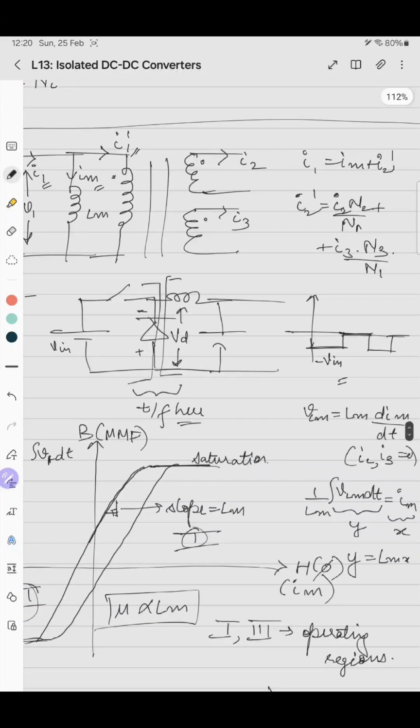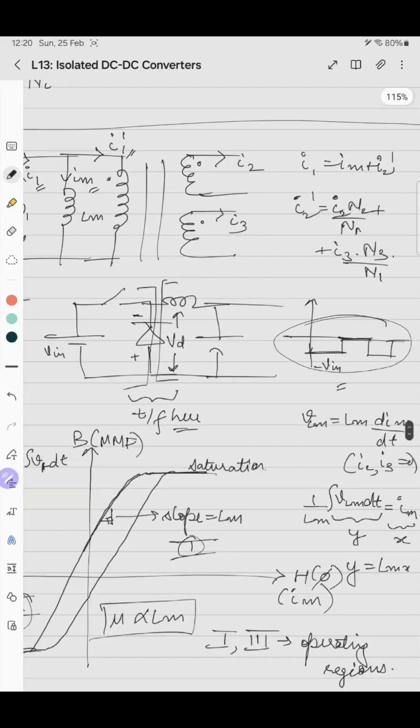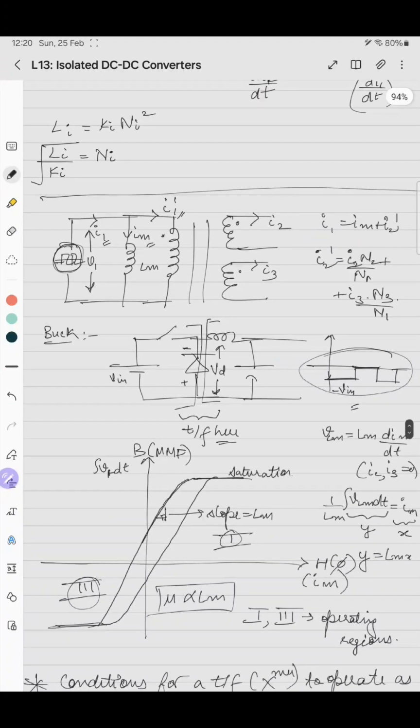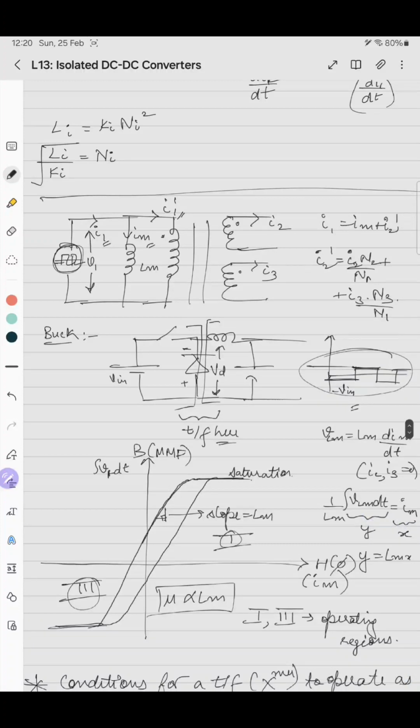then we have to see the voltage. So let's say we insert a transformer between it, and this is the voltage across the diode. So this type of voltage has some average value. So if we add a circuit element between the diode and the inductance as an isolation, which is by addition of a transformer, which means that instead of giving an AC sinusoidal supply, we are giving a square supply or a square wave of zero average value.